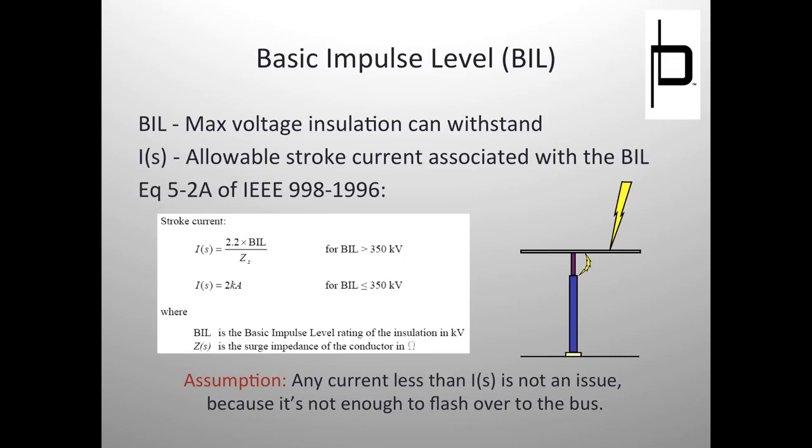I think to get those ratings, they mean like 90% of the time, but there's a lot of environmental factors that would contribute there. Let's say that insulator is dirty or it's wet, that may create a path for current. Or if we do a lot of work near oceans, the salt water from the oceans, or near construction sites, the dust and things like that. All these things that can contaminate the insulator may cause it to flash over much earlier than 900 kV BIL. But again, nothing in lightning protection, nothing that we do is 100% short of the Faraday cage. So for practical purposes, we're going to assume that the 900 kV BIL does what it says it'll do.